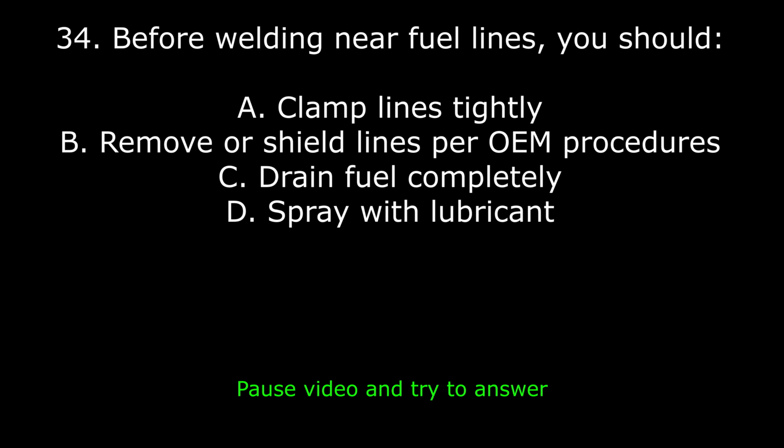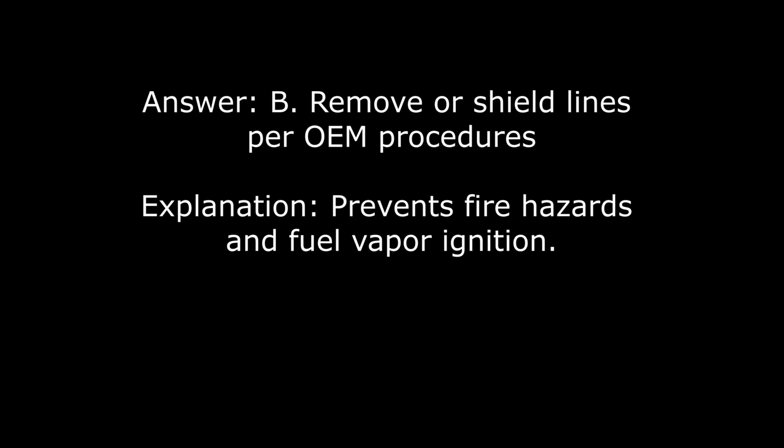34. Before welding near fuel lines, you should A. Clamp lines tightly. B. Remove or shield lines per OEM procedures. C. Drain fuel completely. D. Spray with lubricant. Answer: B. Remove or shield lines per OEM procedures. Explanation: prevents fire hazards and fuel vapor ignition.